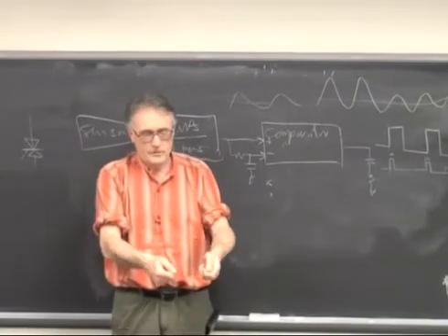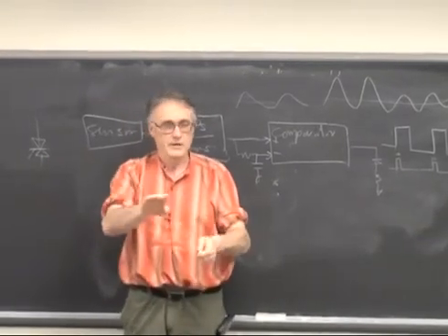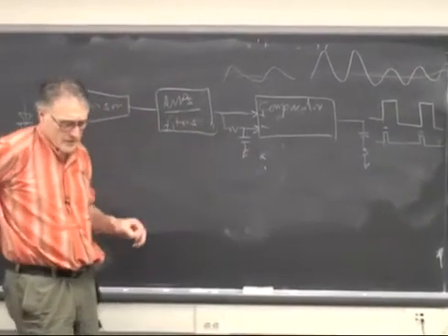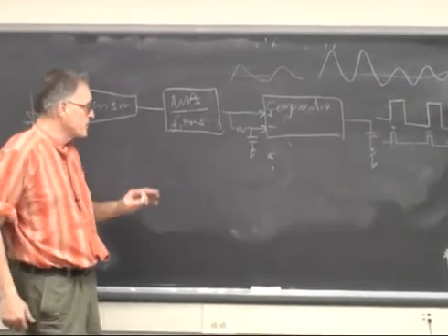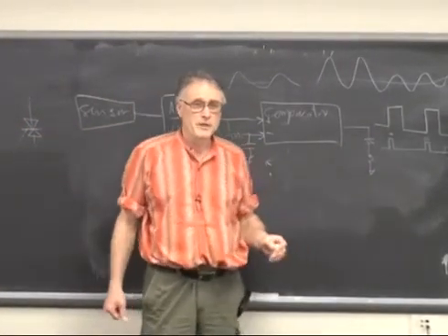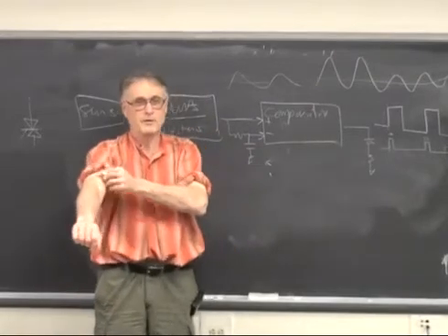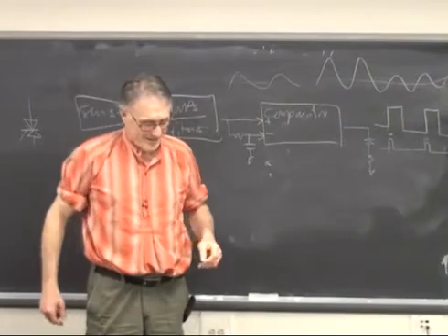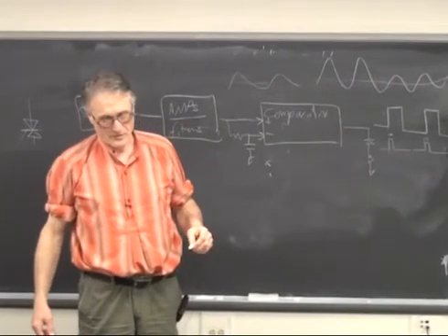Hook up a digital voltmeter to it, and it reads in heart rate. That'd be fun. It's a fairly simple project, but there's other things you could do too. You could put another 555 timer on here and run a beeper, so it goes beep, beep, beep. So all of your partners are foaming at the mouth.